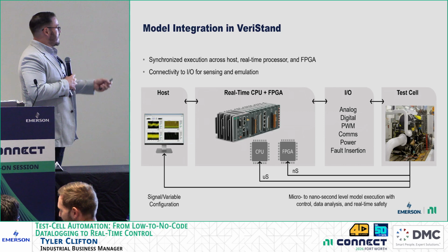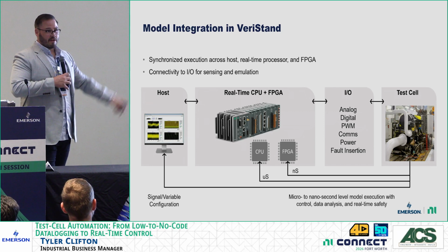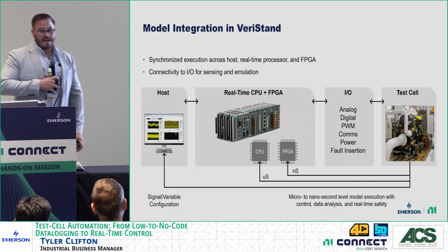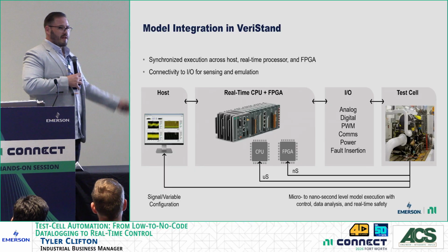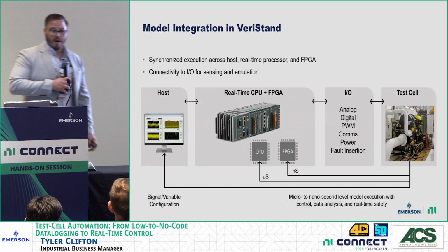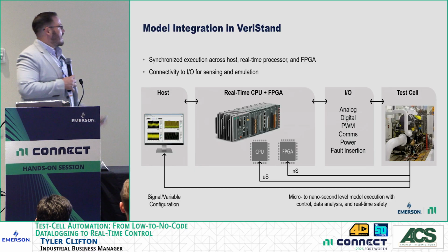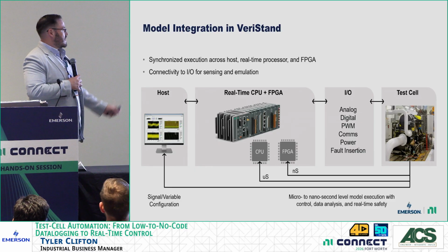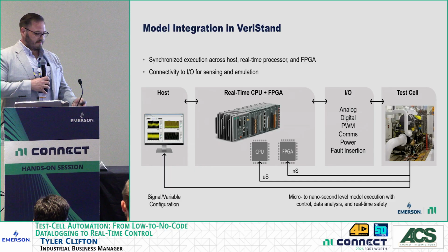If you need nanosecond level response rate, we have the FPGA in our integrated controller in the CompactRIO. If you need something at the microsecond level response rate or even slower, the real-time CPU is perfect for this. All the while keeping it fully synchronized and managing the I/O in our system, the C-Series I/O. That's interfacing our test cell or device under test.